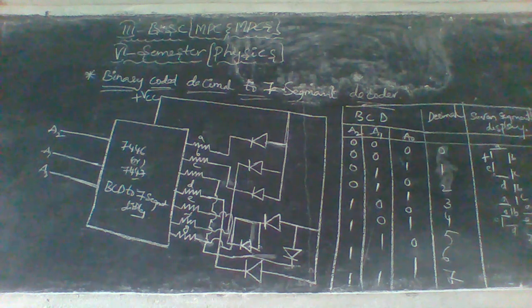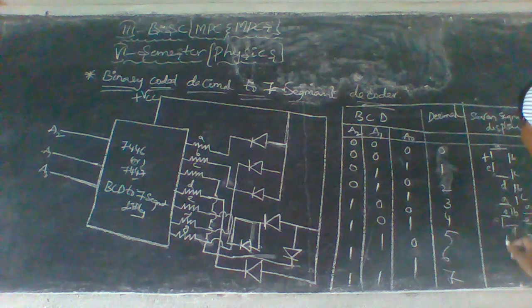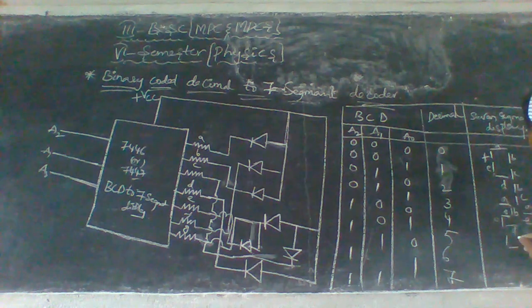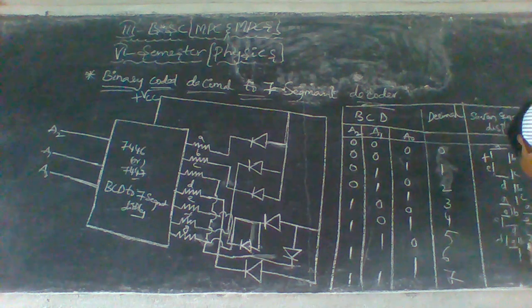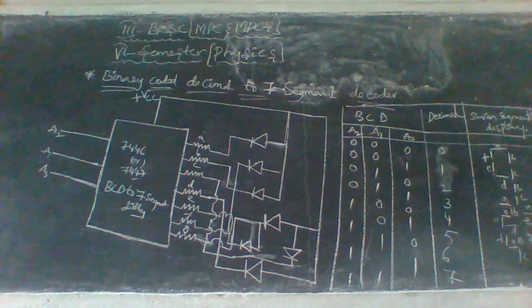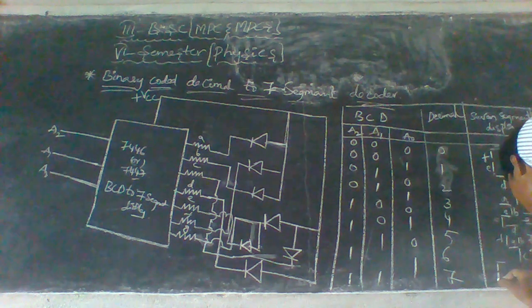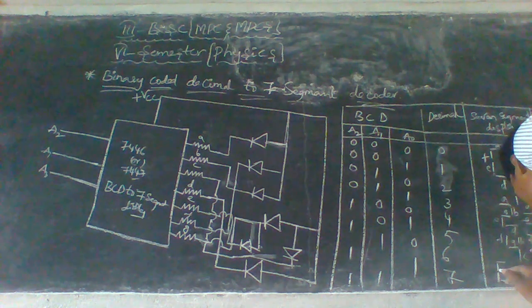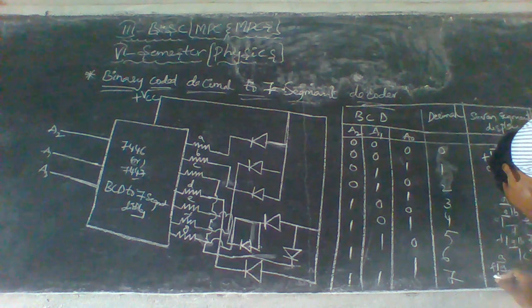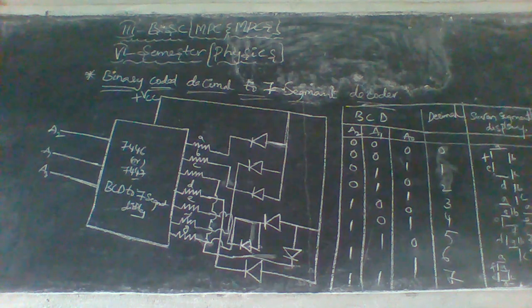And 4 will be displayed on F, G, B, and C. And 5 will be displayed on A, F, G, C, and D. And 6 will be displayed on A, F, E, G, C and D. And 7 will be displayed on A, B, C.